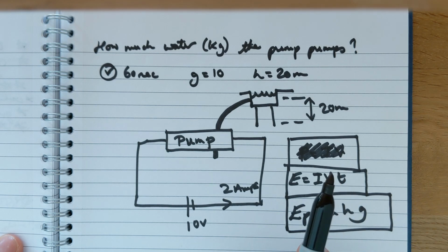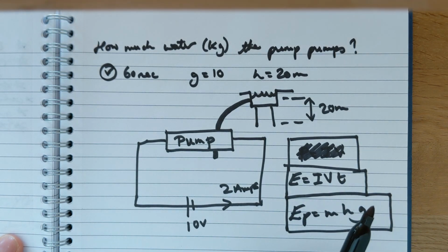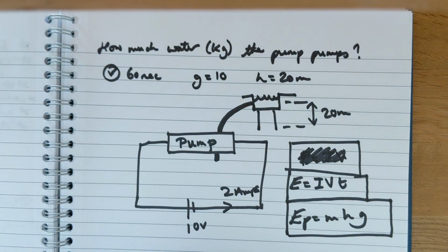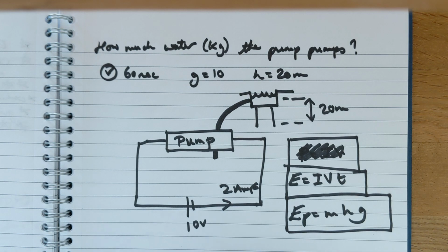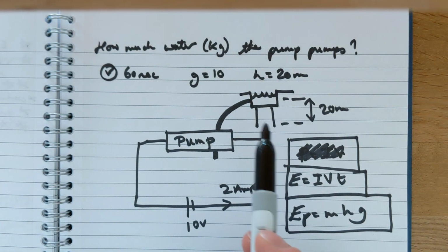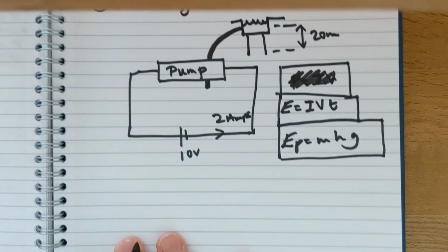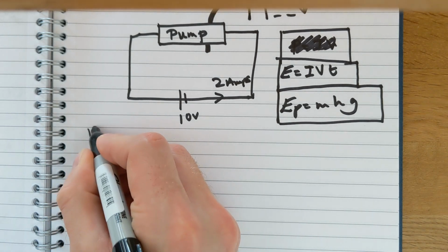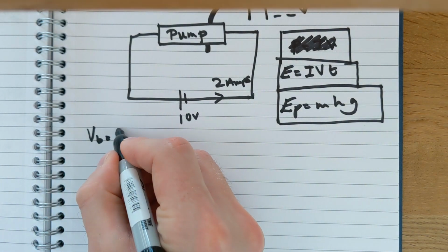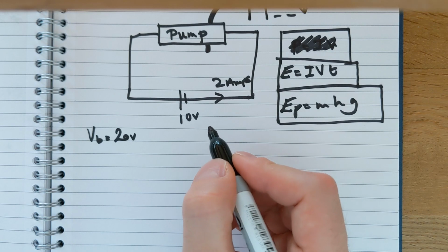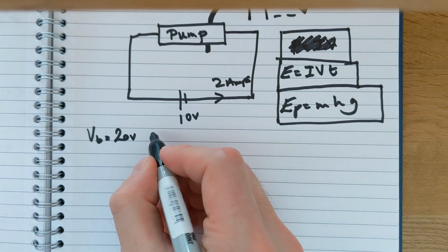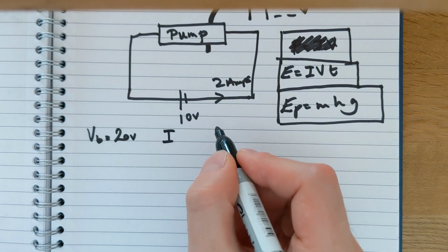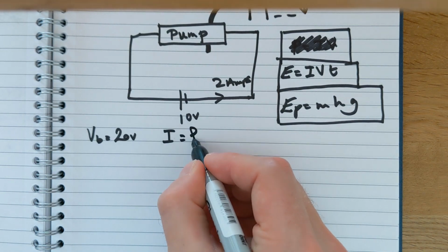So we can arbitrarily choose 6 and define the 7th from the equations. So first things first is to choose our arbitrary bases. We'll start by choosing arbitrary bases for our circuit part of the problem. So let's say our voltage base is 20 in this example, and our current base is, let's say, 8 amps.